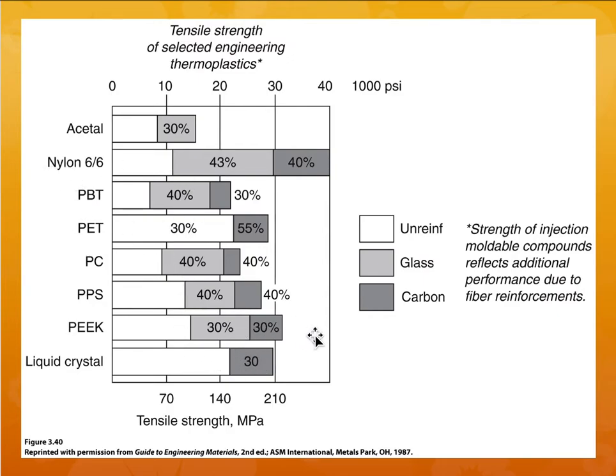The other material is polyaryl ether ketone. It is called PEEK, and the big advantage with PEEK is that it is also one of the most biocompatible materials. So people are trying to use PEEK in bioimplant type of materials. It is very lightweight, so it's not like putting in a titanium implant.